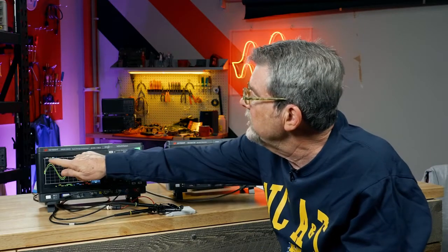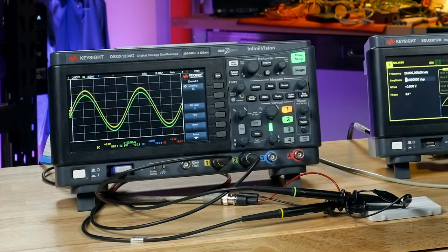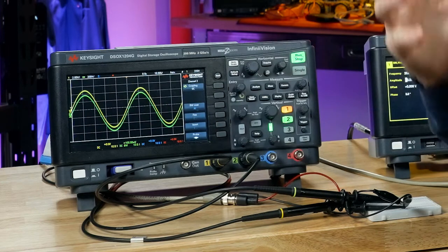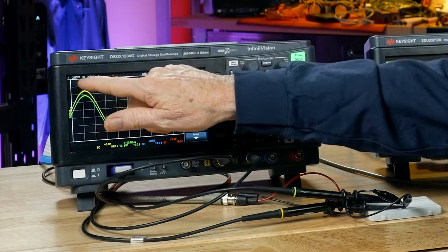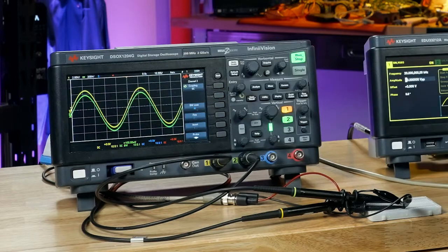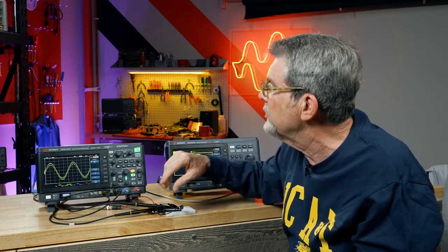Now back to those numbers at the top of the screen. Up here, you can see this says 2.00 V/, volts per division. It doesn't say division, but that's what it means. That's telling you the scaling of the channel 1 waveform. And so we can use that to get an estimate of what the amplitude is of the channel 1 waveform.